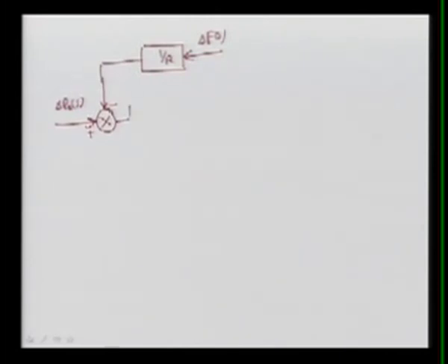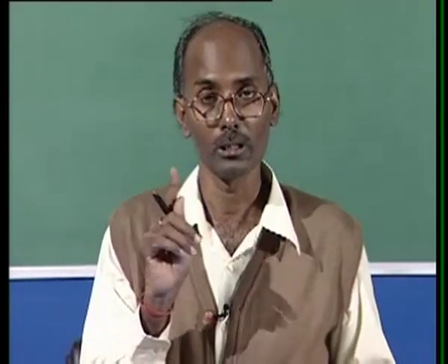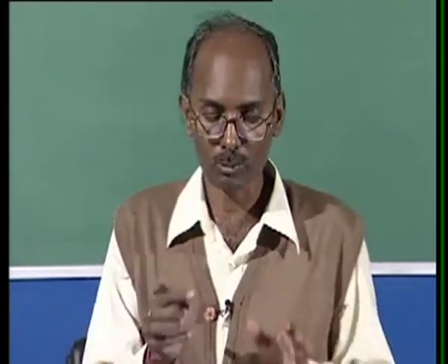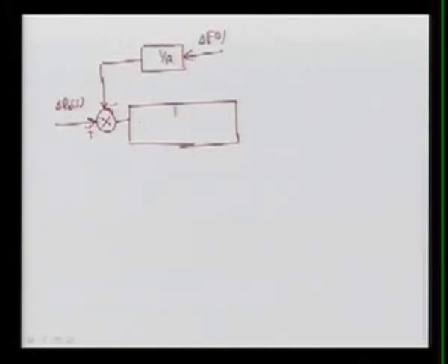So now the governor time constant, and I have to write the governor and the turbine together because I said that Kg multiplied by Kt is kept unity. So both are now coming together. So I can write 1 here, Kg into Kt, over 1 plus Tg, that is the governor time constant, and 1 plus Tt of your turbine, and here we are getting the change in Pt.